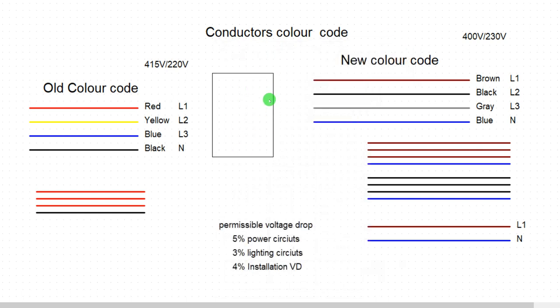So for the power demand of the project you are doing, all the apparatus, circuits, equipment and appliances, as you put them on, you take your readings. The final voltage drop when everything is working shouldn't drop more than 4% of your declared voltage. If you are also working with single phase 230, it should not also drop above 4%. All right, so that is what this clause is trying to clarify.